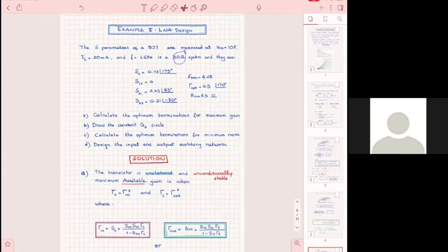The maximum you can do, if you design something around 10 gigahertz, is to go from like 9 to 11, or if you are around 1 gigahertz, to go from 950 to like 1050, all right? That's why some of you saw some crazy stuff, because you were plotting the whole spectrum. No, you cannot do that. All right. So here it's only the scattering parameters at 1 gigahertz only.